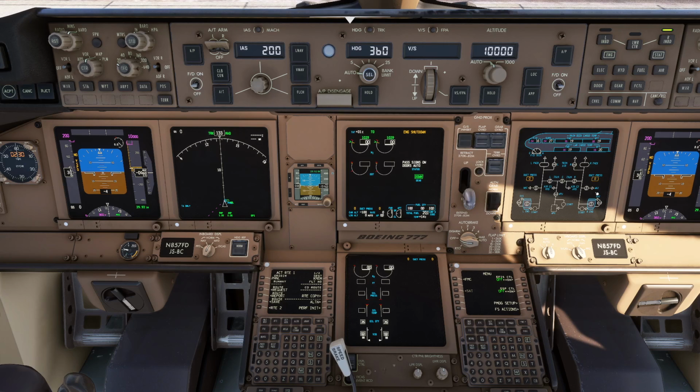And this is the page that we want to pay attention to. So you probably know this, but I'll kind of review this. These engines start using bleed air. That's just a high pressure line of air that feeds into the start valve of the engines. You need to have some source of air, and of course the APU is what typically provides that bleed air to your engines, but our APU is not working. So we've got that problem.